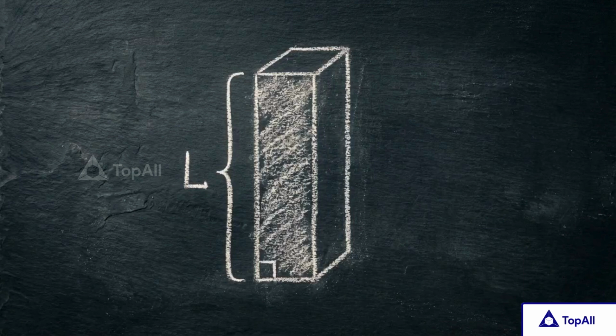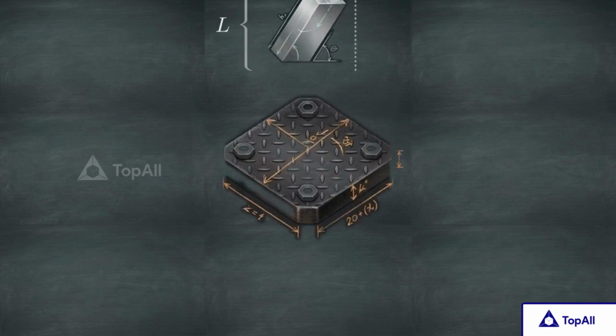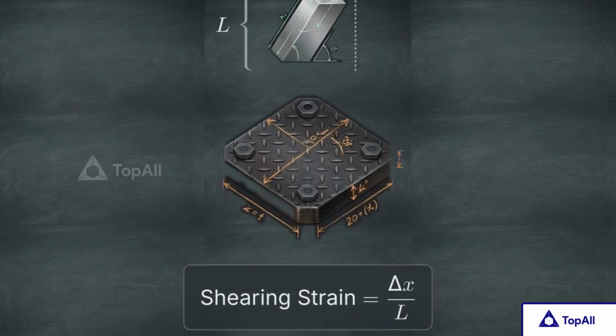We start with the object's original vertical height, which we label L. As the tangential force is applied, the top face moves away from its original vertical alignment. This horizontal shift is the relative displacement, denoted as delta x. Mathematically, the shearing strain is defined as this displacement divided by the original length L. This displacement also creates a clear angular change in the object's geometry. We define theta as the angle of tilt between the original vertical posture and the new slanted edge.